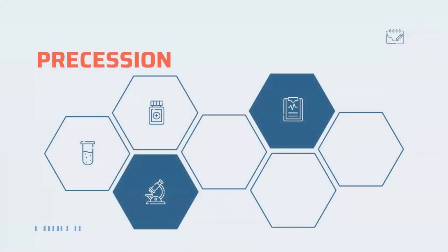The second characteristic is called the precession. When the rotor rotates with a high angular vector, if outer moment is applied to the outer gimbal axis, the gyroscope will rotate about the inner gimbal axis. If outer moment is applied to the inner gimbal axis, the gyroscope will rotate about the outer gimbal axis. The direction of the angular vector is perpendicular to the direction of the outer moments. This characteristic is called precession.